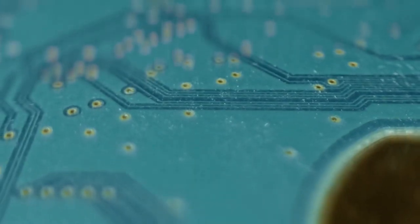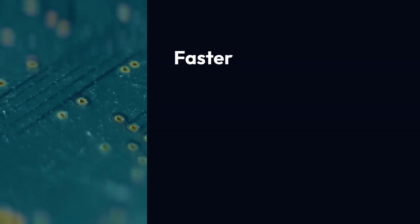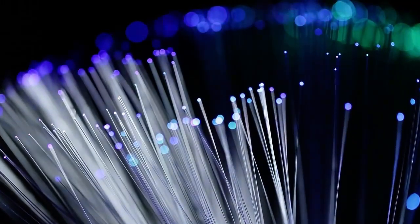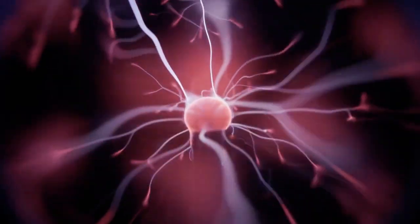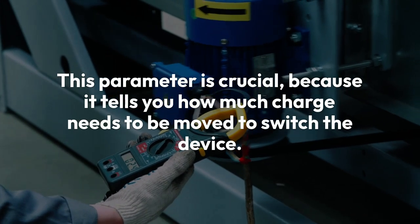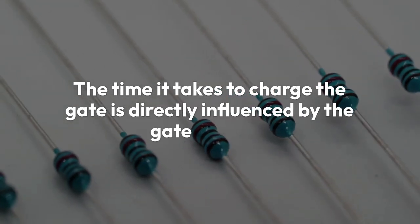Second, think about the desired switching speed. This is often the most critical factor. Faster switching reduces conduction losses but increases switching losses and EMI. Slower switching does the opposite. You'll need to check the MOSFET or IGBT datasheet for its gate charge, QG. This parameter is crucial because it tells you how much charge needs to be moved to switch the device. The time it takes to charge the gate is directly influenced by the gate resistor.